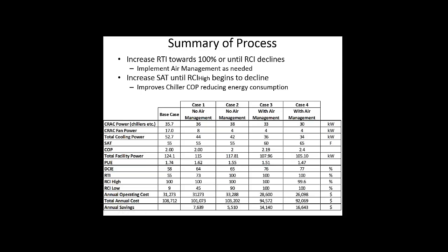It does depend. If it's a chilled water system, you can modulate it easily. If it's a DX, a direct expansion unit, you can't modulate that airflow much other than to turn it on or off. Newer systems do allow you to modulate it 30-40%. And that's all we've done here is modulate it 30-40%, so not too bad.